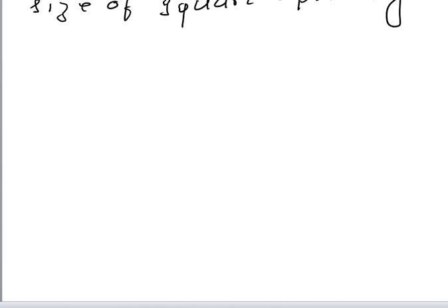So now let us proceed. We are looking into mechanical or coarse grain analysis. What we do is we place some standard sieves. First of all, note the standard sieves used.